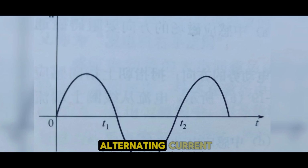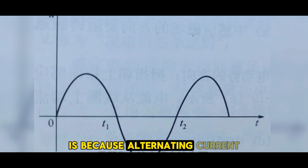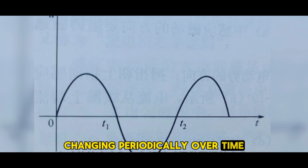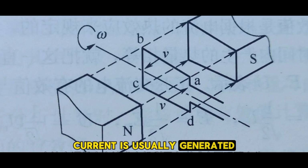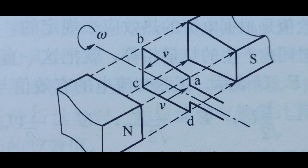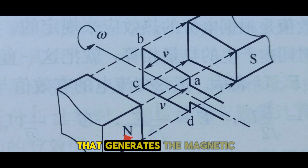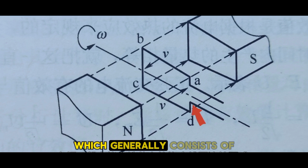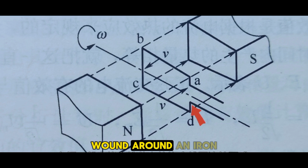The reason we call it alternating current is because alternating current involves the magnitude and direction of current, voltage, and electromotive force changing periodically over time. Alternating current is usually generated by an alternator using the principle of electromagnetic induction. An alternator mainly consists of two parts. One is the magnet that generates the magnetic field, and the other is the electrical output, which generally consists of many coils wound around an iron core.